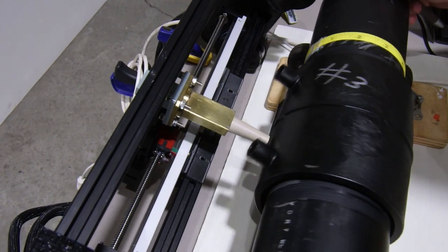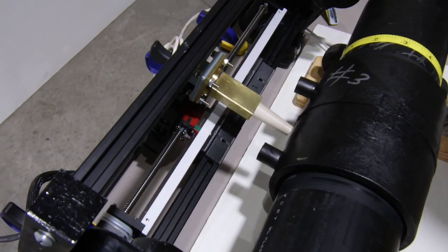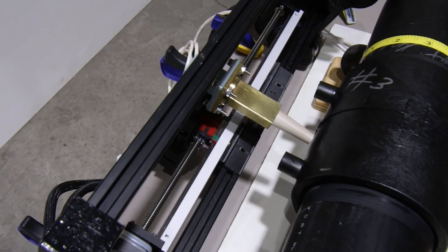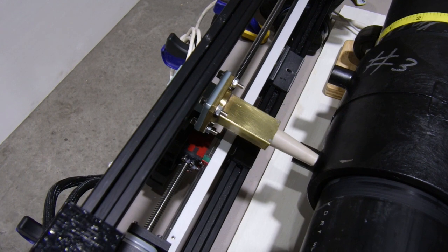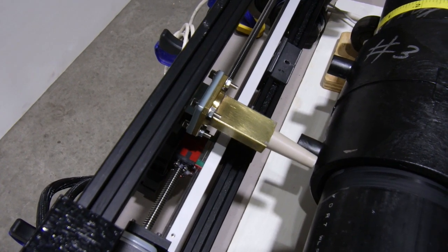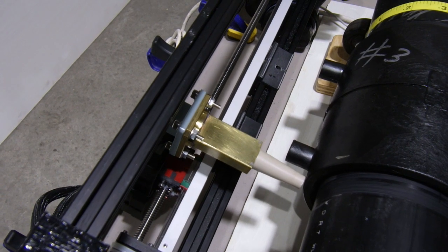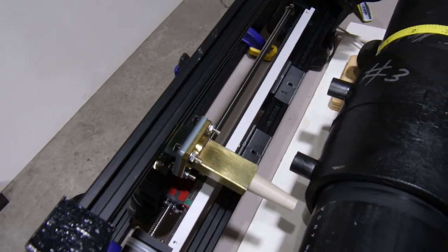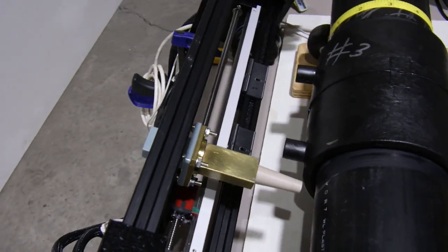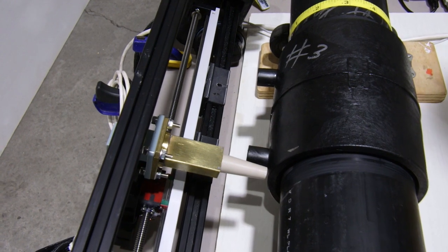So let me rotate this pipe to the start position, and we'll move the encoder and antenna back to 0. We usually do this as a 2-step process where we move it to generally the end of the coupler, and then I want a little extra room for scanning so that we can clearly see the end of the pipe. Now that becomes our 0 point, and we'll hit start and begin collecting data on this coupler.